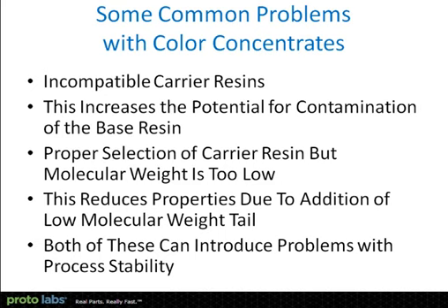There is no such thing as a universal carrier. Let me be very clear about that. If there were, we could mix polymers together a lot more freely than we do, and if somebody dumped ABS in your polycarbonate, it wouldn't turn into delaminated mica in your molding machine. Most polymers do not like to mix. Very few combinations mix well. And when you put polyethylene into almost anything else besides polyethylene or an ethylene-based copolymer or polypropylene, you have incompatibility.